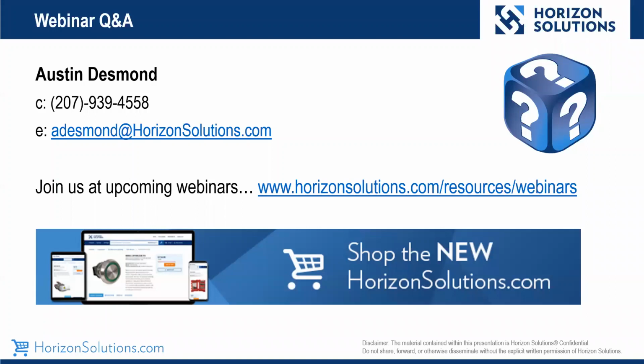However, Rockwell does provide a nice document, and it's actually included, I believe, with the selection of items you will be getting to download here after the webinar. And it's a nice little lab that walks you through and explains all of the default settings for a safety task. If you utilize the default values for the safety task, this can get you started in your design. However, when doing that, oftentimes you should apply a safety factor into that.